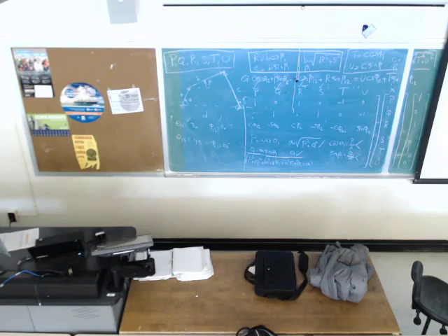What would be theta 1? Sine of theta 1 is Q divided by A. Cosine of theta 1 is P divided by A. Q is 0.8911 divided by 1.02, and P is 0.497 divided by 1.02.